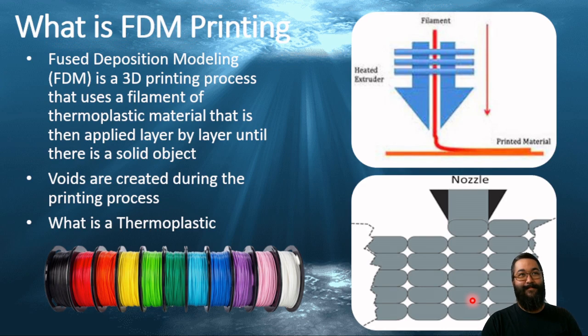What was the reason why that capstone was leaking? So once water finds one of these voids, especially with pressure, and gets pushed through, it will find its way through and out the other side.